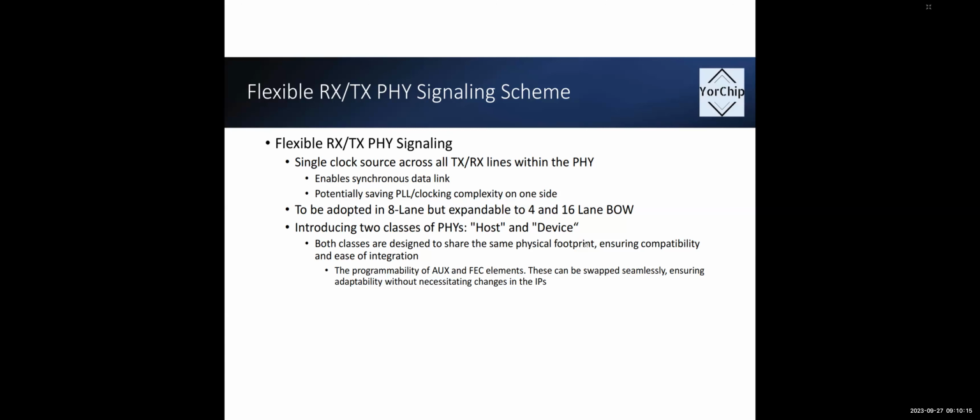I'm sorry. I was just going to ask, are you implying here that the receive side is to use its own clock recovered, or do you mean that you just want to loop around the received clock and use the route of the transmit clock in the other direction? We're basically routing around the clock that, quote unquote, you get from the receive side, but we won't call it the receive side anymore because it's not necessarily only going to be received.